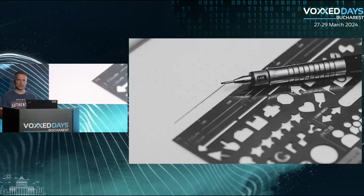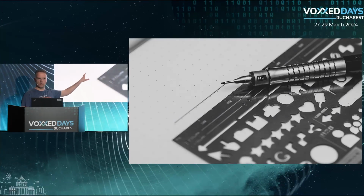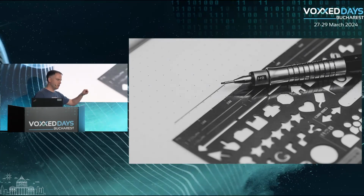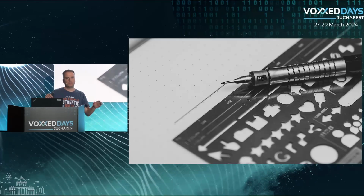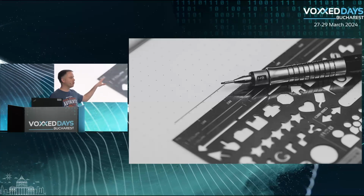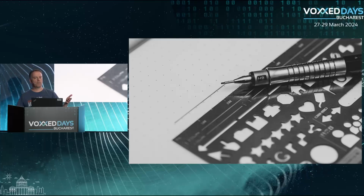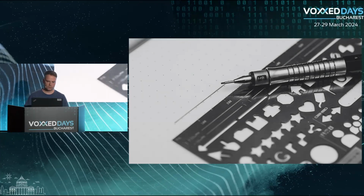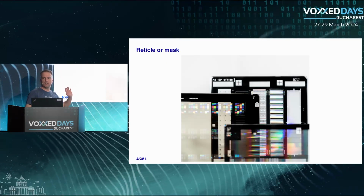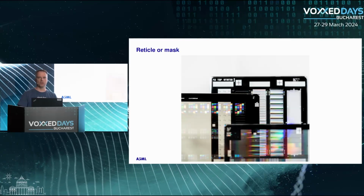So what's that reticle? It's a bit like a stencil. You probably, when you were a kid, have used this to draw some letters or something on a piece of paper. The parts that are open you could draw in, and the rest you can't draw because it's covered. It's the same for a reticle. It has the pattern of one layer of a chip on it, and on some parts the EUV light can shine through, and on other parts it can't shine through. And then you have a reticle that looks like this. It's a bit more expensive than the templates that you used at home. One of these reticles costs about $250,000.